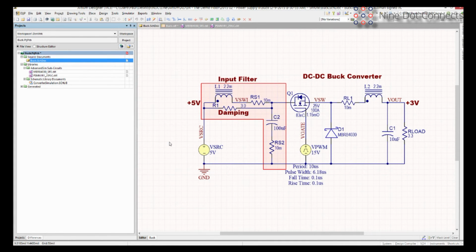Now, in addition to that, you do have to add some type of power sources to it. So you have things like this VSCR, and all the simulation libraries, by the way, are provided with Altium. If you go into the examples directory, you'll find all of these. There's, I think, 4 or 5 of the libraries specific to SPICE simulation.